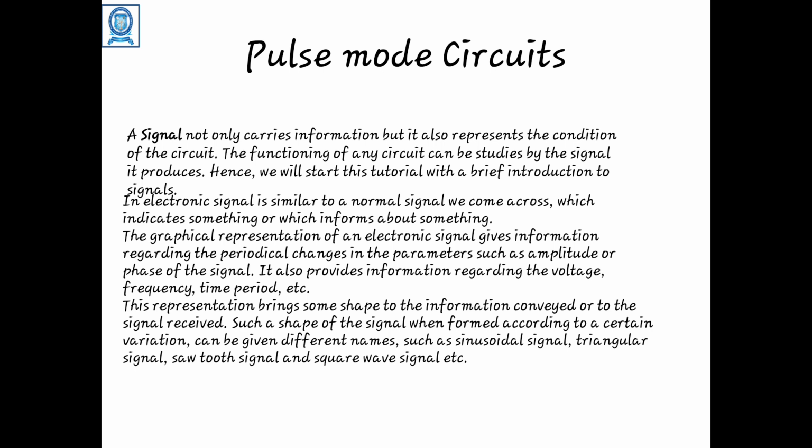We already know that in synchronous sequential circuits, memory elements are clocked flip-flops. But in asynchronous sequential circuits, memory elements are either unclocked flip-flops or time delay elements. You have to know these two major differences between synchronous and asynchronous sequential circuits. Therefore, in asynchronous sequential circuits, a change in an input signal can affect the memory element at any instant of time.